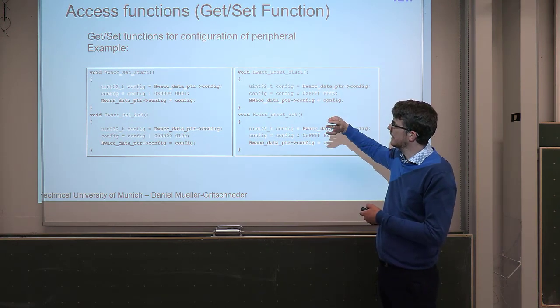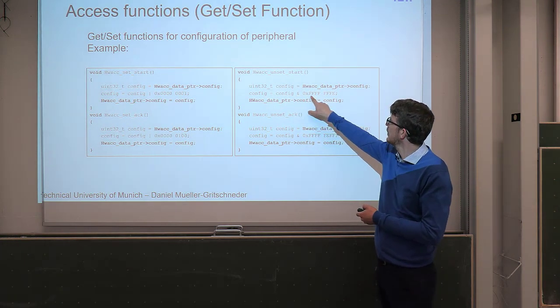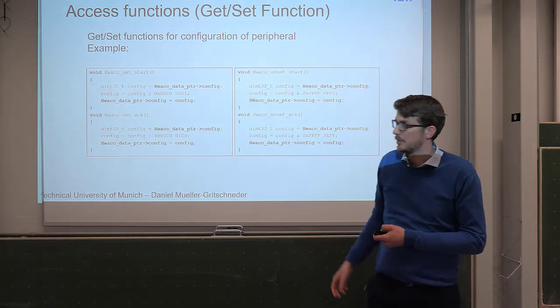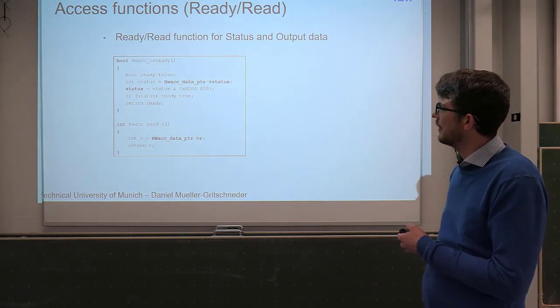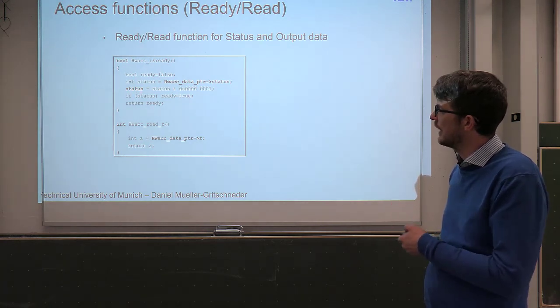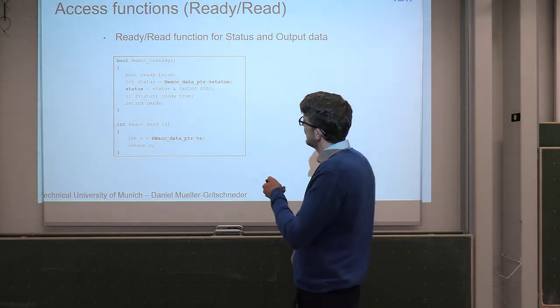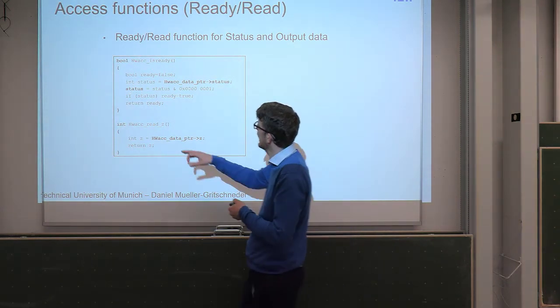So if you want to unset it again for the next computation, you just make an AND with this constant, and this would just clear the lowest bit and set it to 0. Okay, but what we actually would be doing is, the computation has run, and then we could just check, is it ready? And if it's ready, we are reading the status register,